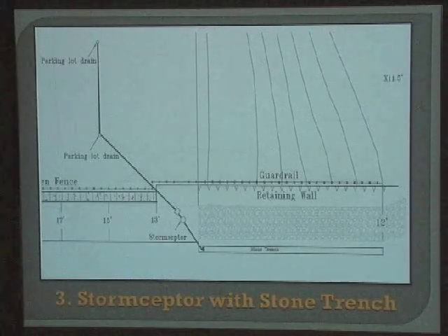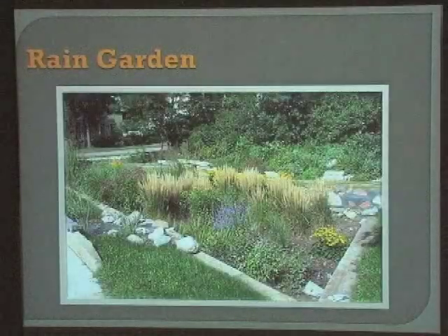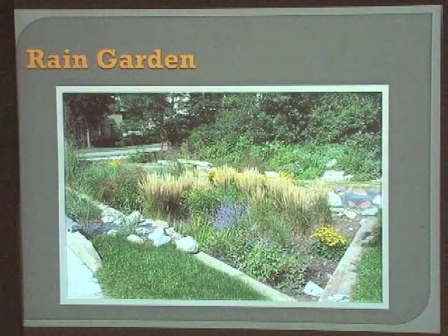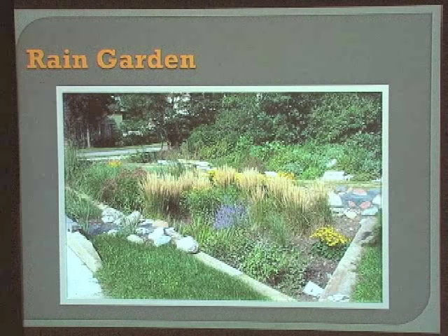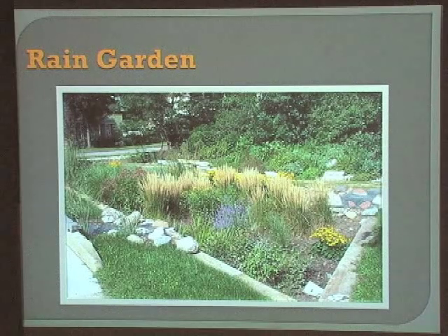Our final concern was the roof runoff polluting the surrounding waters. So all roof runoff is passed through rain gardens, which take advantage of local plants that absorb any harmful nutrients that may be contained in the roof runoff. Jimmy Medina will now be talking about our roadway design.